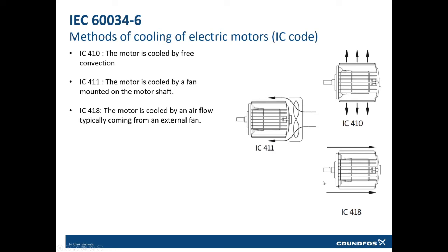This usually happens in submersible pumps, these borehole pumps. The cooling of the motor is not given by a fan, but it is given by a flow of water. Because if you know, this is the borehole and this is the motor of the submersible pump, this is the suction, and these are the different impellers. Sorry, I put it wrong. This is the motor and this is the impeller, the different impellers. The water will come here, go through all of the motor, cool it down, and leave the pump.